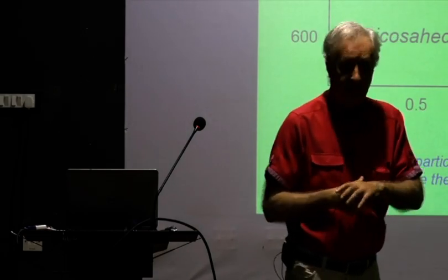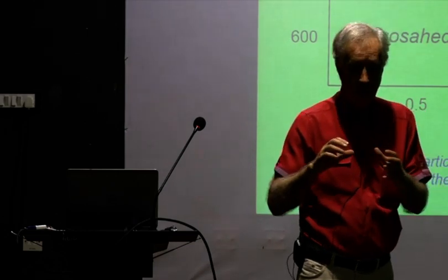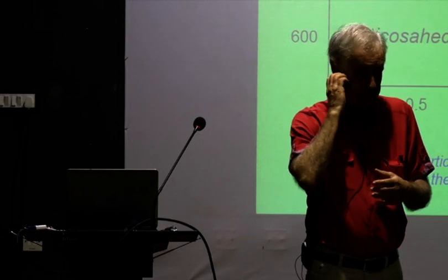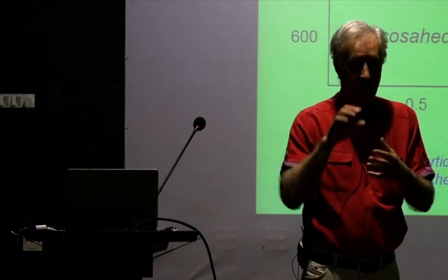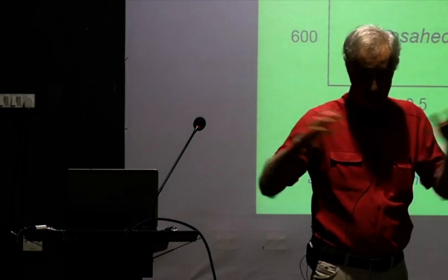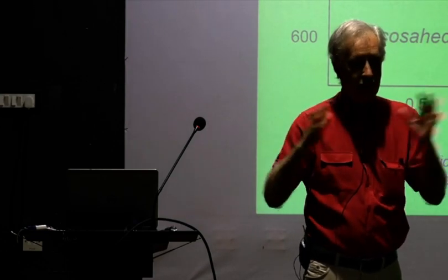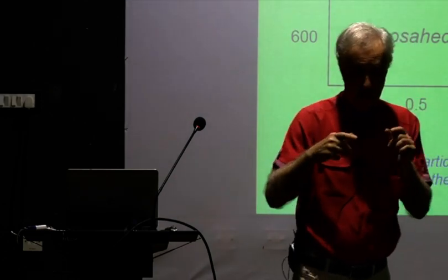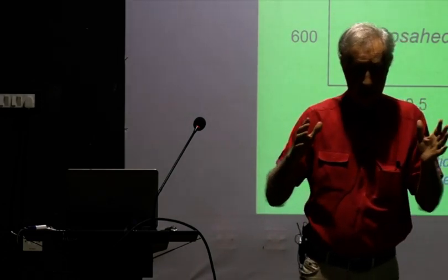It's an antiperovskite, and the nitrogen sits in the middle. The reason nitrogen can go into the octahedral void and sit there is the anti-invar effect. You can expand FCC iron in all directions very easily. It has this tremendous enhanced anharmonicity, which I tried to show you yesterday. So you can make this.